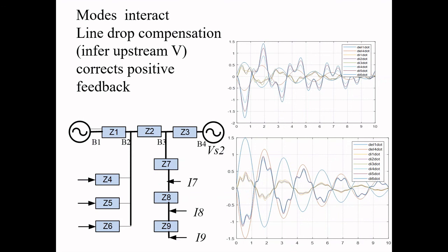But the evidence to date has been of a substantial increase of robustness over just using terminal volts. Yeah, I think they're definitely a step forward than just using the local voltage. So it's better, definitely better than local voltage. And plus, there are also the broadcast reference signal that could help. If you use the broadcast, then you're, in a sense, not dependent on any Kalman filter modeling to be able to know what you should do.